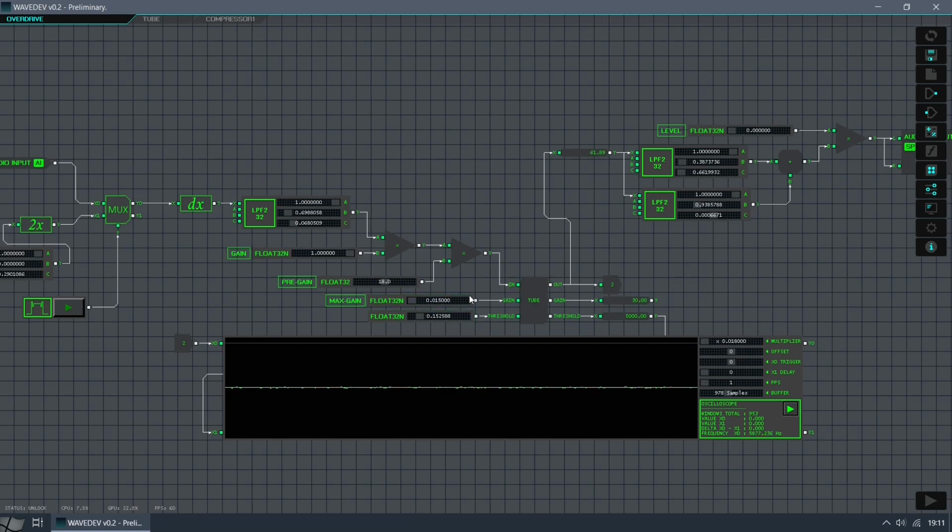Regarding the saturation stage, we will limit the gain. I estimated that a gain of 30 times the threshold is quite enough for this effect. You can define higher limits, of course, but I think there's no point in sounding again like distortion. Without the two high-pass filters, going beyond this gain will quickly spoil our effect. The overdrive effect should not completely destroy the natural guitar sound.